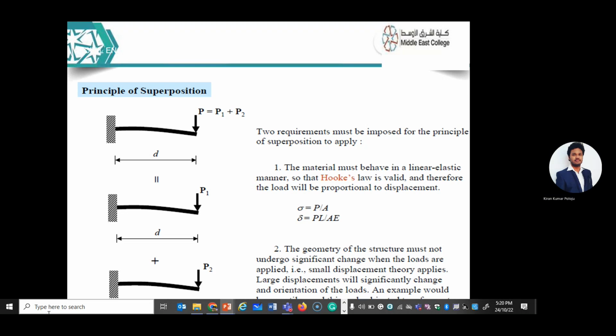And you have already calculated the original length. So whatever change in length you observe at each point, let us say 0.1 is the change in length at some point, then the strain at that point is 0.1 divided by the original length. You will get the strain at that point, and Young's modulus is stress by strain. There are around 10 to 15 points.